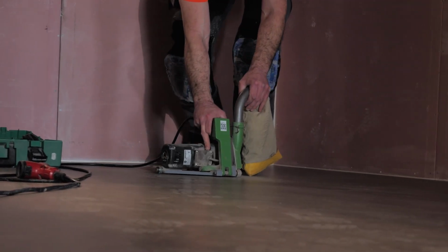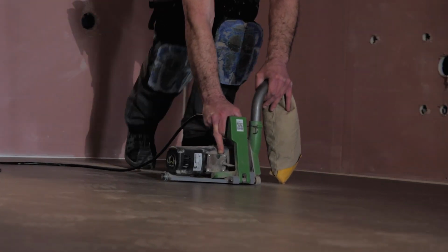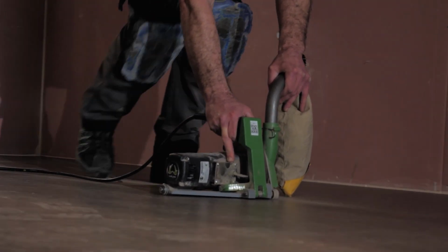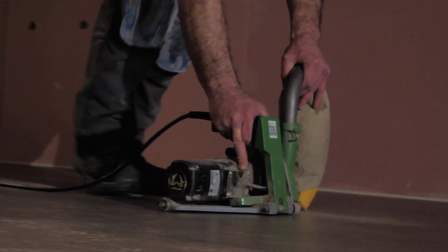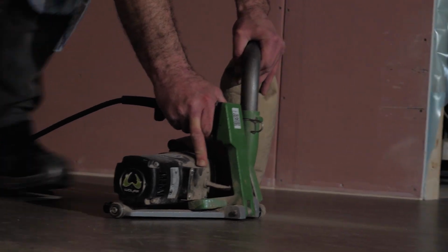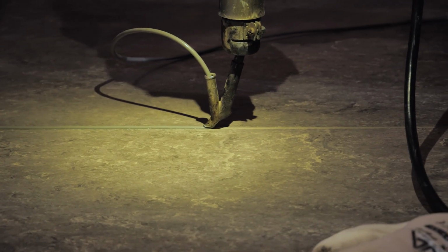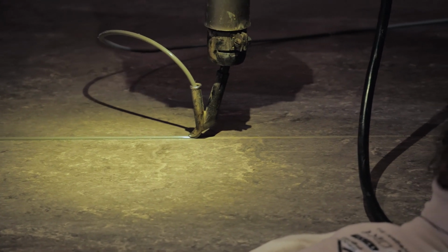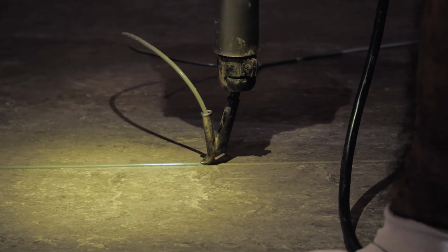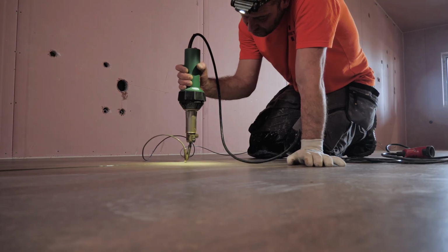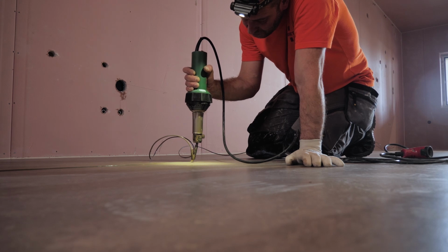Once the covering is installed on the floor and the adhesive has dried for at least 24 hours, a groove is cut into the covering seams to install a welding cord to seal the seams and ensure the floor's durability. The welding cord is installed hot using a suitable tool. The welding seam ensures the tightness of the floor covering and must be installed according to the hot welding work instructions.